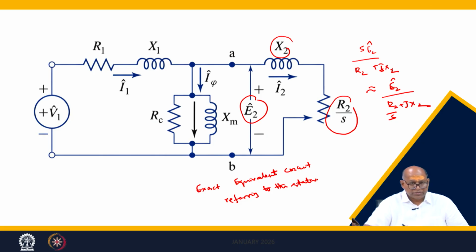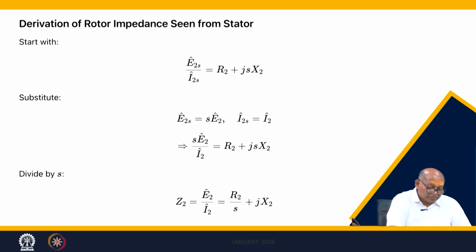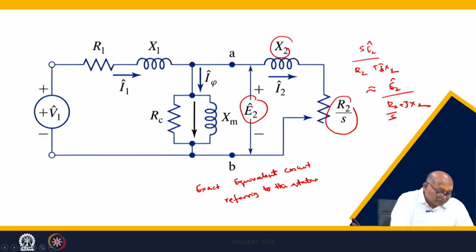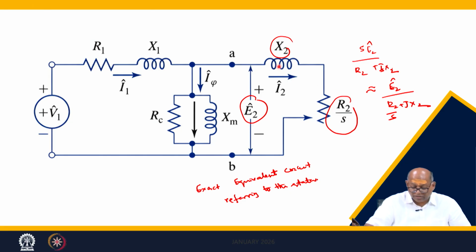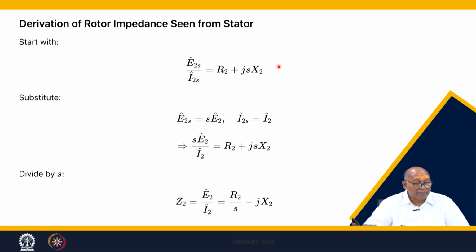All right, we have to use this equivalent circuit, this is per phase. So, you can compute power, whatever power goes in, there is some loss here, some loss here. Let me use the pointer. There is one loss here, another loss here, one loss which is because of resistance, and the rest of it goes as mechanical power.